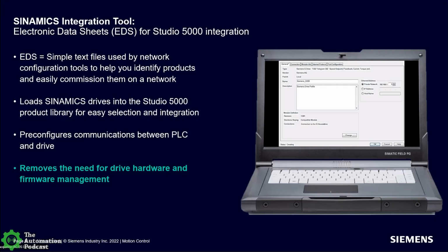And what this allows you to do is easily select our product. It pre-configures communication between the PLC and the drive. And then we've developed these EDS files so that you don't need to manage hardware and firmware. So we disabled keying for the drive.